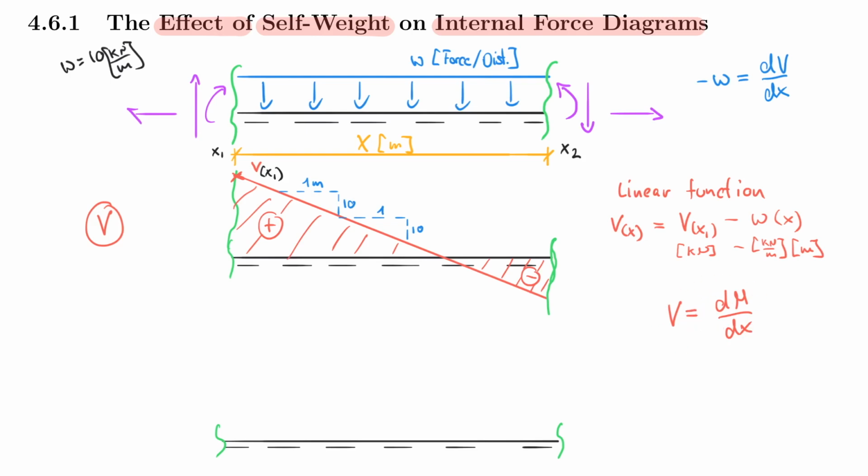So what we want to do is end up with the moment diagram here on the bottom, which of course goes hand in hand with this function here. And since we already see this relationship, we can, at least conceptually, integrate. You can do it mathematically too, but sometimes there are traps you will fall into. I talked about that in the last lecture, but remember that you can integrate from the shear force to the moment diagram.